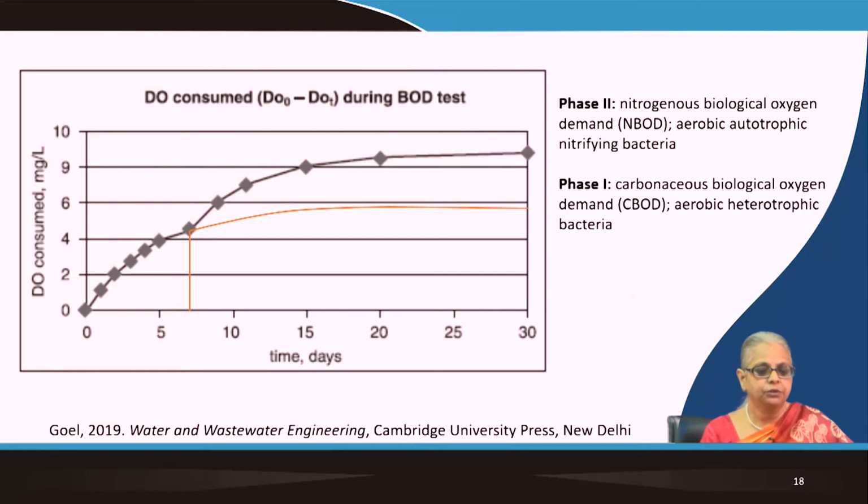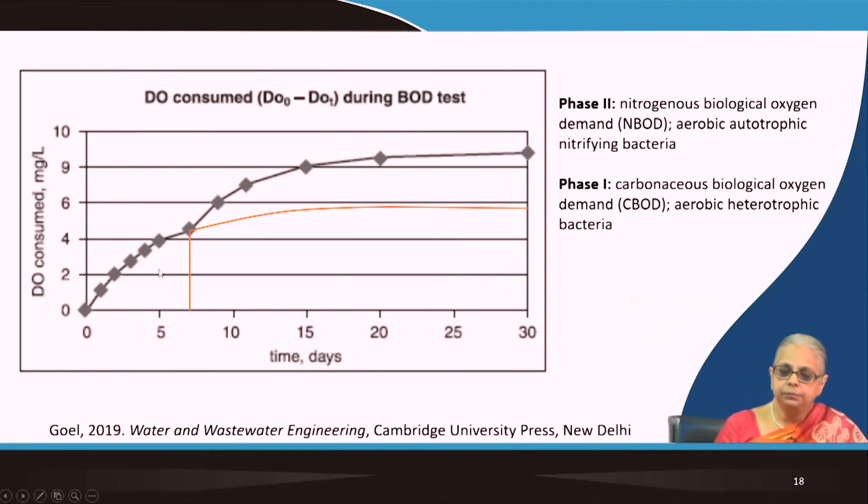So here we have the results of a hypothetical BOD test. Now in a BOD test, we normally take only initial DO concentration and final DO concentration, and once you know what your DO saturation is, you determine the concentration in the sample and you will get your DO consumed by subtracting it. Okay, so DO0 minus DO at time t. Like I said, that's a simple 2-point test.